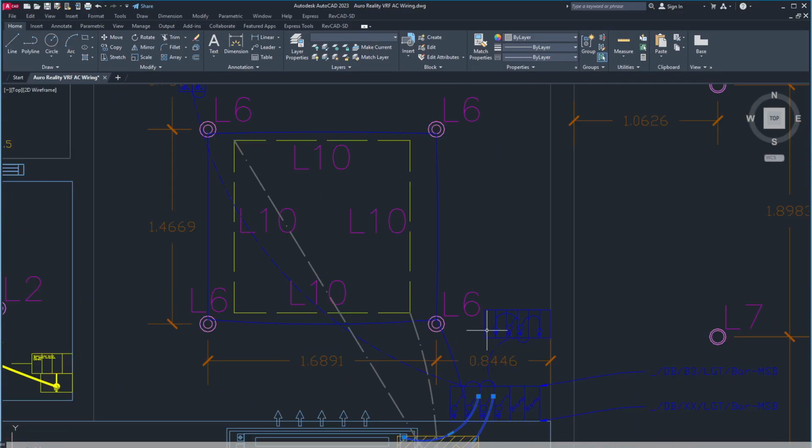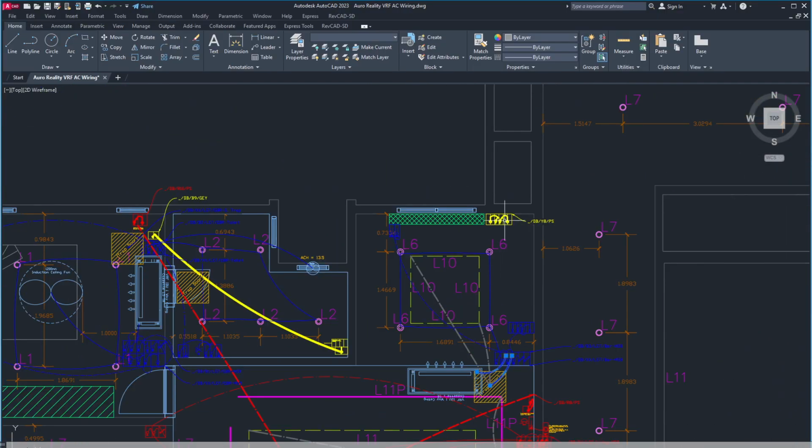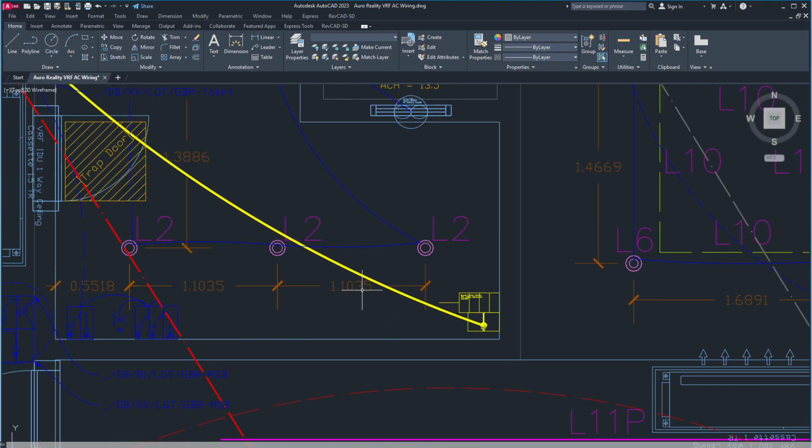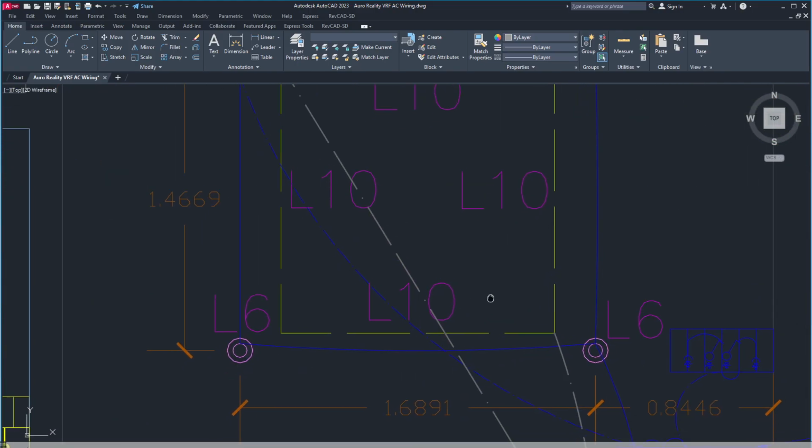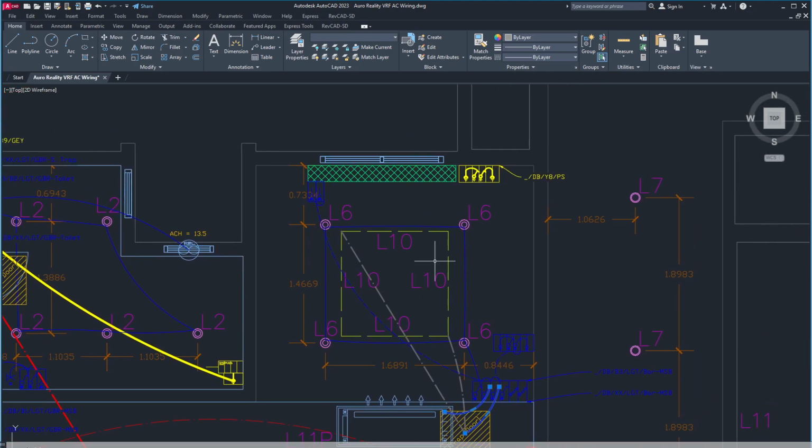See, this is in a blue phase. This is yellow phase. If it is yellow, it is Y phase. Blue phase, B phase. We have three phases in electrical engineering in India: R, Y, B, red, yellow, blue. So we try to divide our loads on all three phases so that the load is balanced.